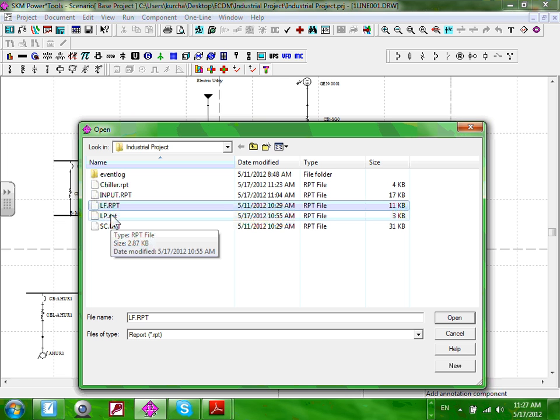Then I need you to do the coordination curve for the chiller and the coordination curve for MP. Instead of MP, can you say LP, because we did an LP, just to make it easier for you. It says MCC, cross out the MCC and put lighting panel, LP. This is on page 3. We used to put an MCC at one time, we moved it out. So we're going to make it lighting panel, LP.